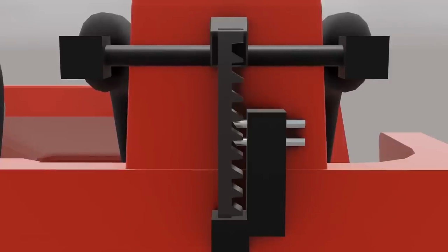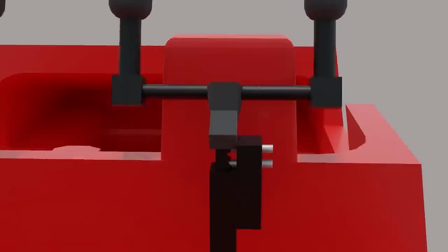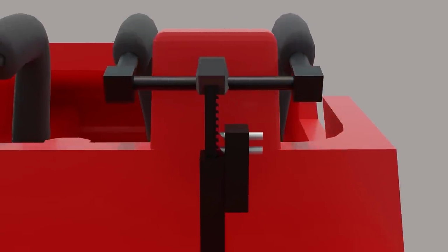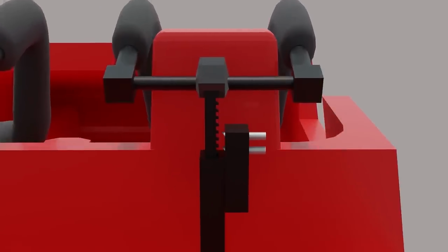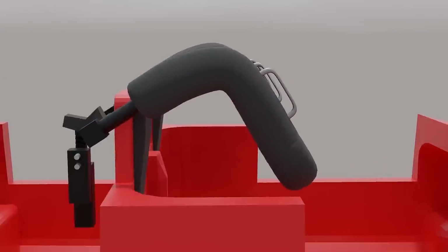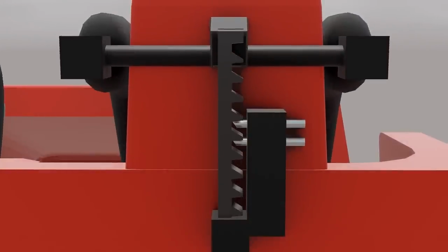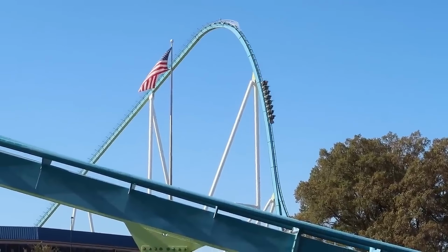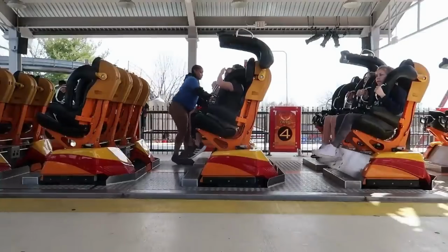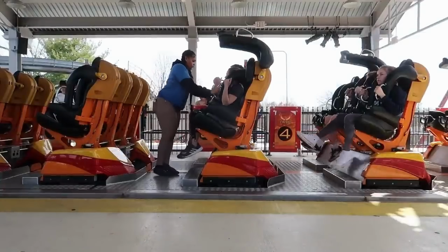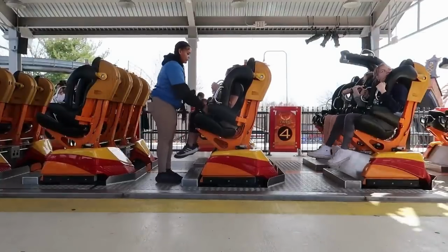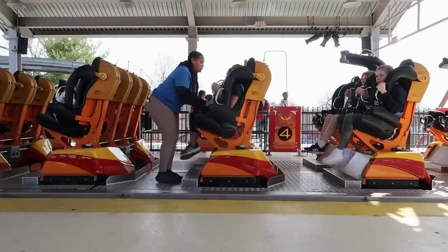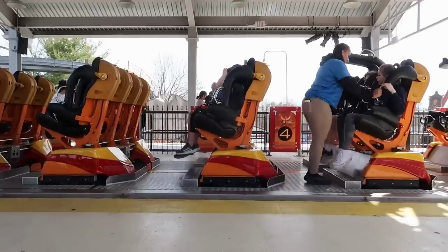This in turn allows the rider to lower their restraint at any time, but it does not allow the restraint to become open until an outside entity interacts with the system. The locking pins are spring-loaded into position, requiring force to remove them from the locked position. In this way, the ratchet design defaults to the locked position, making it considerably safer than the latching restraint. More advanced versions of this design, such as those found on B&M roller coasters, use a drum-like ratchet with several hammer pins. This restraint design does suffer from one flaw that has resulted in them slowly fading away, and that is that they're only able to lock in a predetermined number of positions.